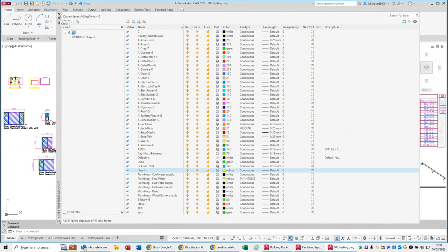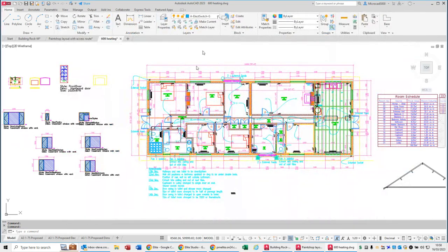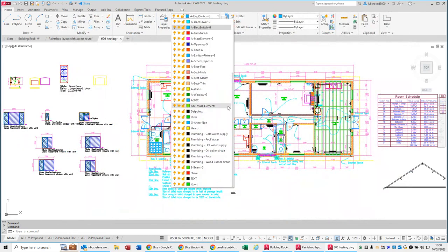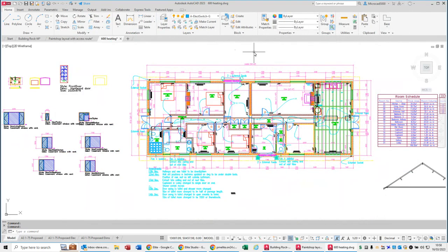Okay, so yeah, was that layer on last time? So you're turning layers on and off in the list there, trying to remember. Well, the tool to sort that out for you is a tool called the Layer States Manager. What you can do is create a snapshot of the current settings of the layers. So here, for example, all the layers are turned on. It's a bit of a mishmash on the screen.